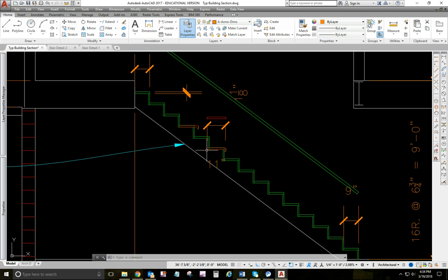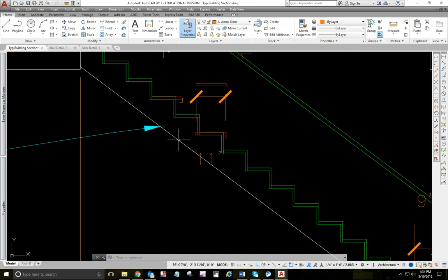Now, the materials used in building a stair, of course, the stringer, which is the bottom part here that gets cut in this zigzag, that is typically a 2 by 12. That's normal. In commercial construction, it can be almost unlimited as to what you will find, but normally in residential it's a 2 by 12, which means it's 11 and a quarter inches maximum from the straight edge to that little corner right there, 11 and a quarter inches.